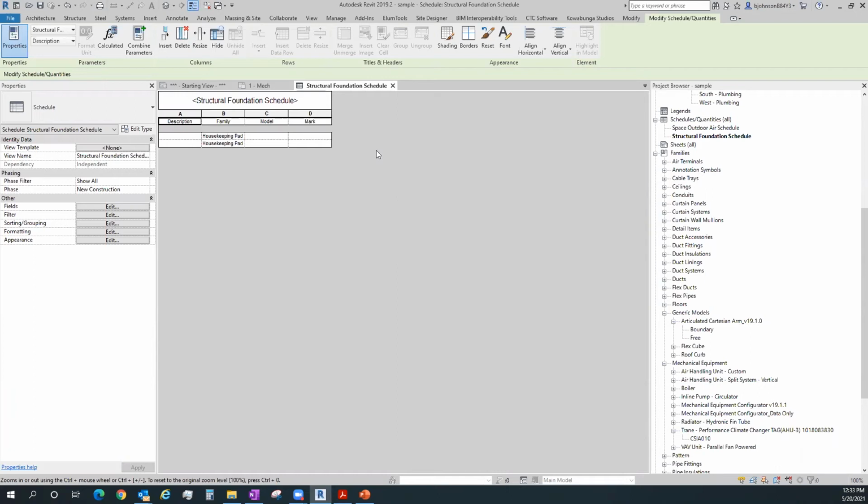try to evaluate what your Dynamo script is doing and how it works, and then if it needs to be rewritten or add new nodes or whatever that might be, get the extra scripting tools from lots of other developers out there that have developed ways, either Python or C# ways or something like that, of making their Dynamo scripts work correctly. There's a lot of stuff with the API that isn't fully open, in my opinion, to Dynamo, to what you actually really want it to do.